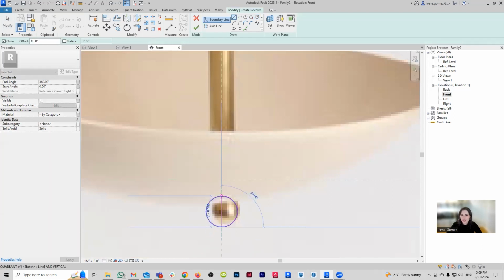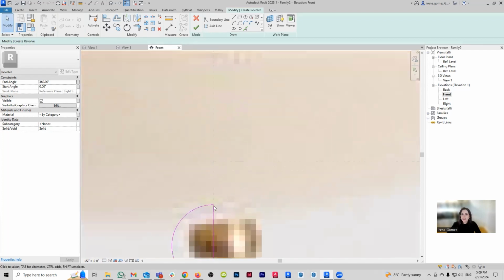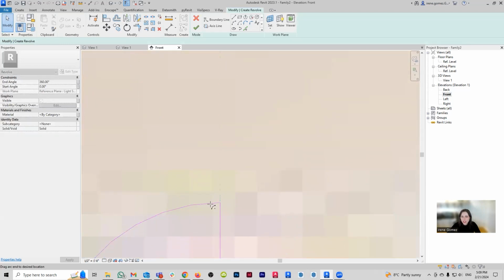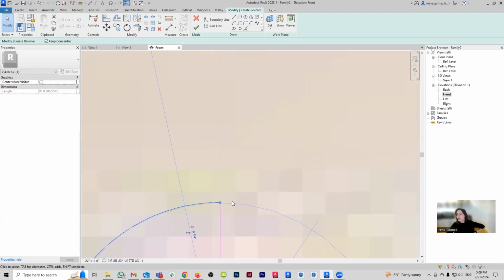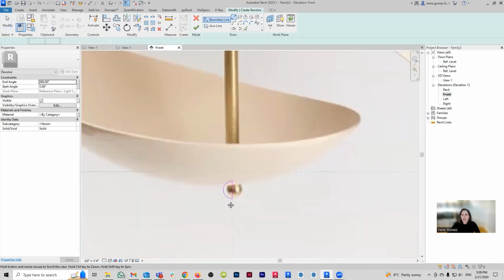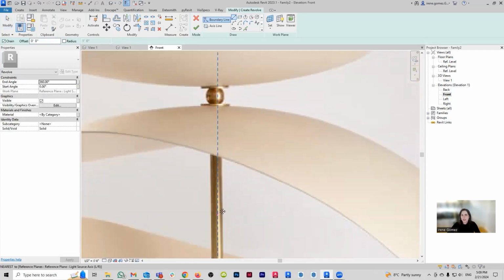I'm going to bring it here, cut it, SL for split, and then TR, trim. Now, one thing that we're going to be careful with is I'm actually going to make my arc just a little bit shorter, like I'm going to be using the split. The reason for that is that, for example, let's say that I have one of those little rectangular elements, like the little plate that we see here.